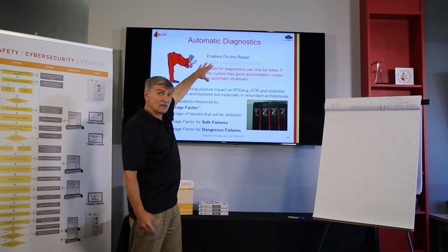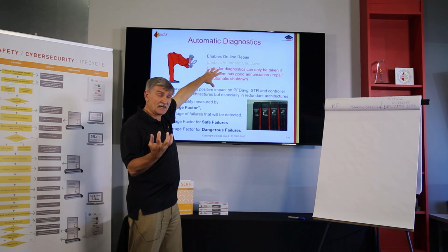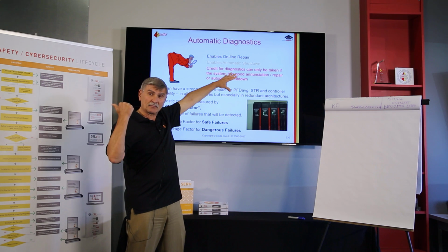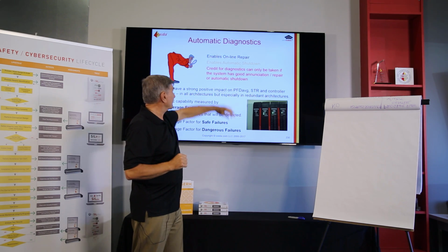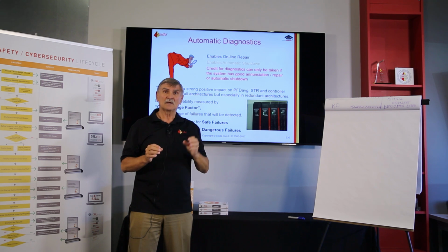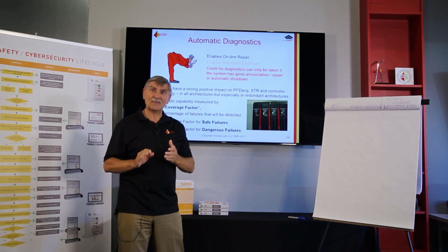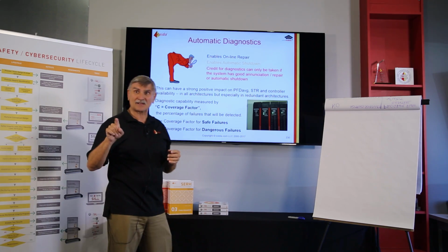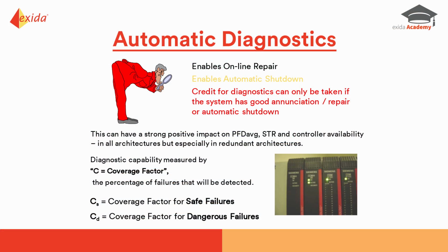It enables online repair, automatic detection of the failure, tell the repair people, come and fix it. It enables automatic shutdown. If you need to shut down on a dangerous failure, program the automatic diagnostics to do exactly that. And we can build new architectures by using the automatic diagnostics.